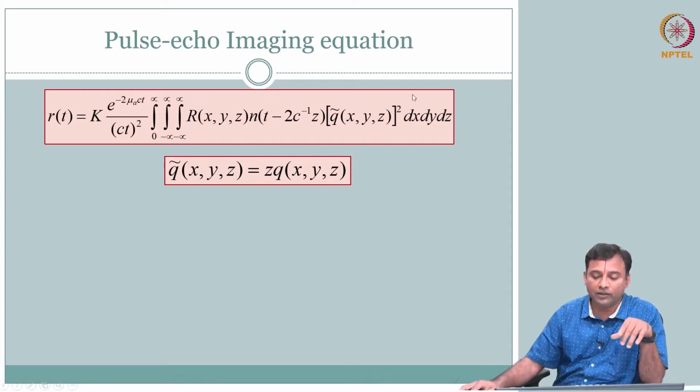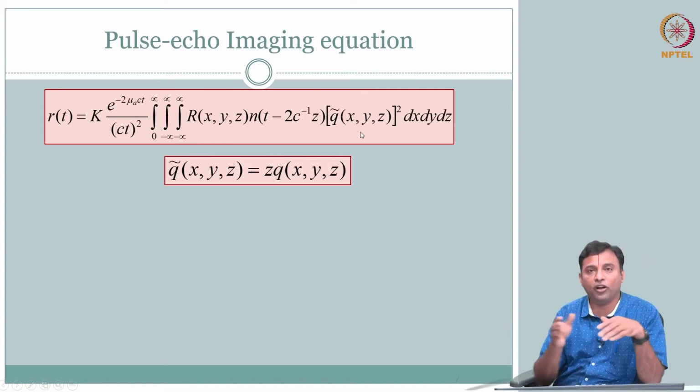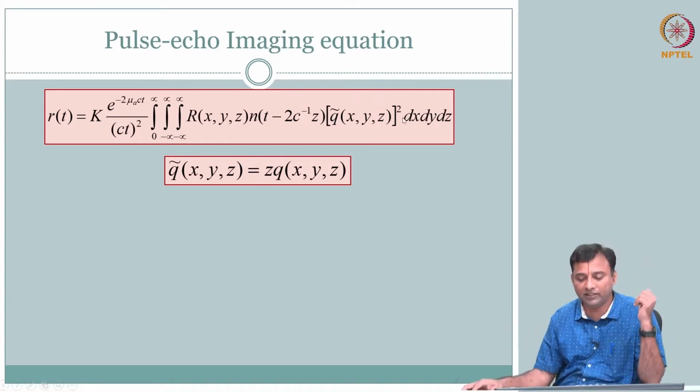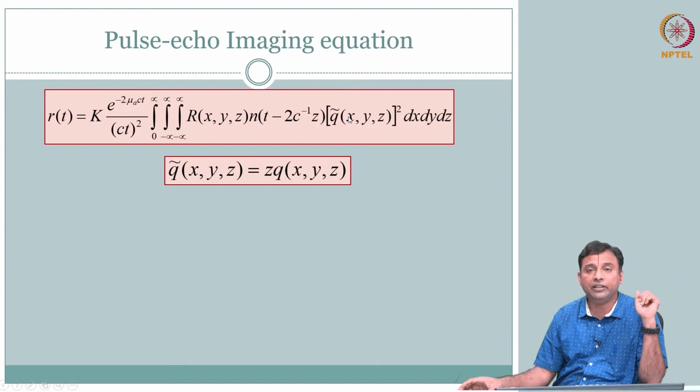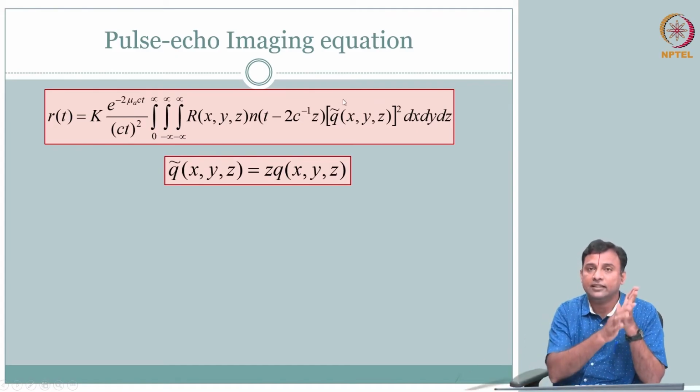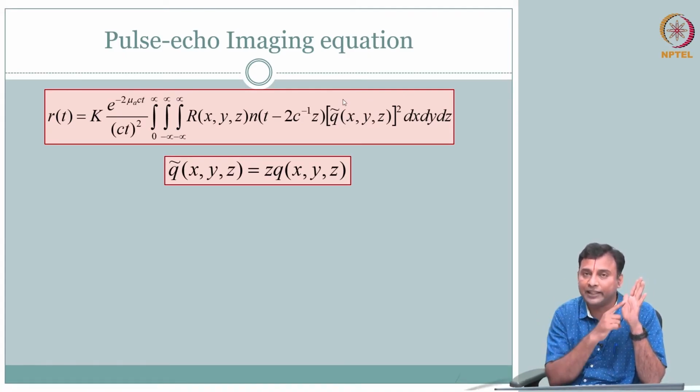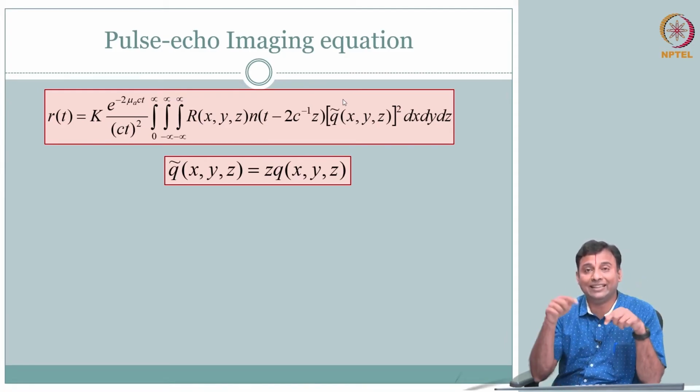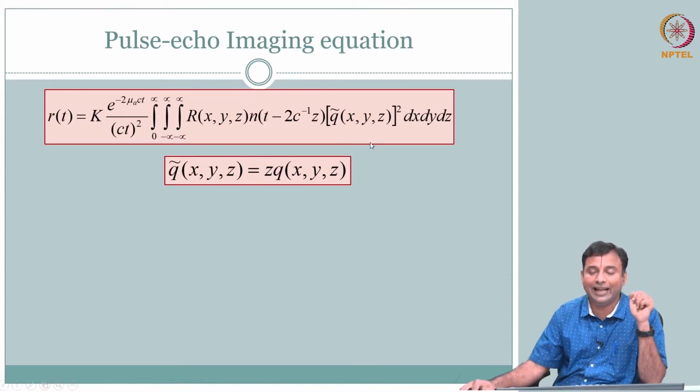In fact, we covered what this is in the Fresnel zone, Fraunhofer zone, near field, far field. We played with this Q. We told that in the far field it is essentially a Fourier transform of your transducer shape. So, if it is a circular disc, then you get a Bessel function; if you get a rectangular disc, the rectangular shape will give you sinc in 2 dimensions. So, this is your directivity. We talked about main lobe, side lobe. So, this is your beam pattern, if you will.